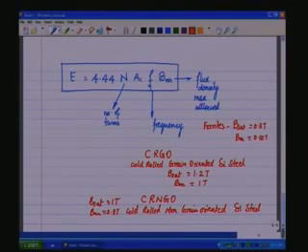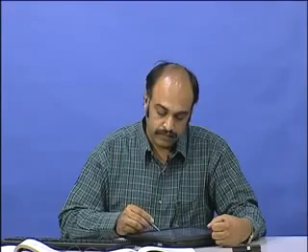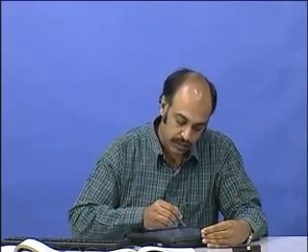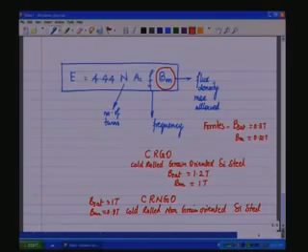So, for different materials, there are different B sat values, which are an inherent property of the magnetic material. The operating flux density swing should be less than the B sat value. So, that is the value that has to be used in the design equation.